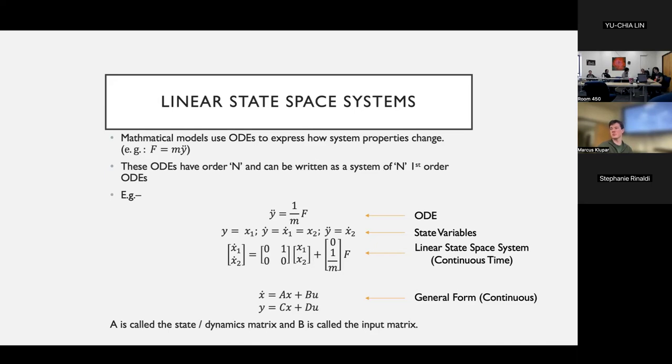So you're going to have all your conduction terms. If your instrument's attached to some metal bulkhead or whatever, you're going to have a conduction term for each one. And you're going to have your radiation boundary. Each wall is going to be a different temperature. That's all super key for coming up with your thermal control.